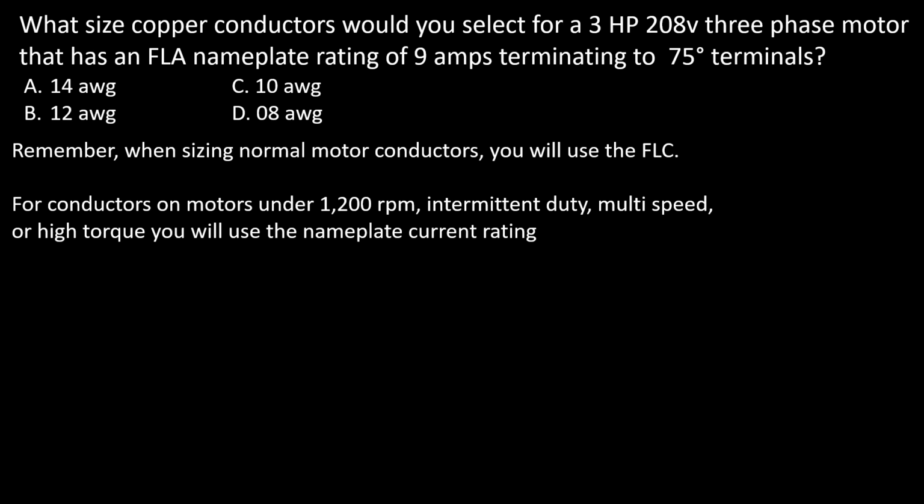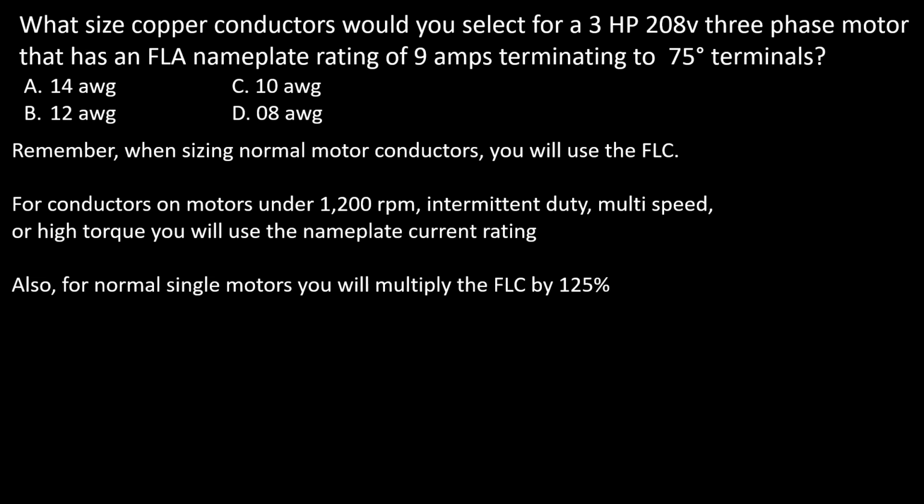nameplate. When we're dealing with a certain special set of motors, we will actually use the FLA nameplate. I wish the code book wasn't like this. I wish they would just pick one or the other and stick with it, because it makes it very hard when you're testing. But I'm going to teach you this week and reteach you, because remember, we've learned this in the past. This is the Master Series. This is all about you already knowing this much, but I do want to recap so it's fresh on your mind. All right, so let's go ahead and jump in. Also, when we're doing normal single motors, we're going to multiply that FLC by 1.25.